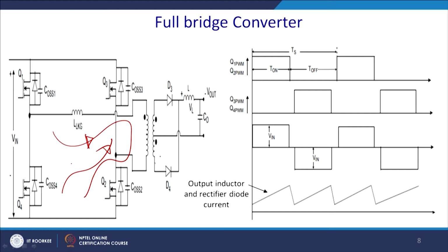So, what happened here is quite simple, and it has the maximum power handling capability. The transformer gets the whole voltage, and thus you can have a better utilization of these voltages. Mostly this is applied for high power applications, and the core is the smallest considering the kVA rating of the transformer.